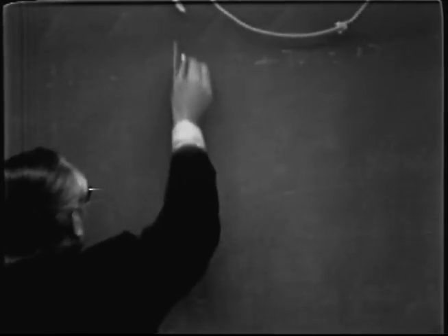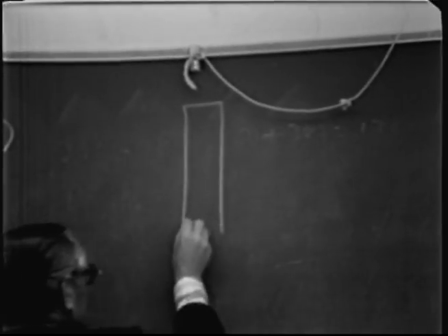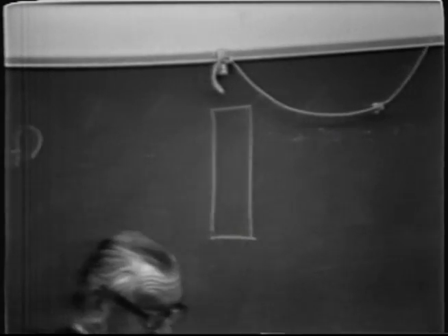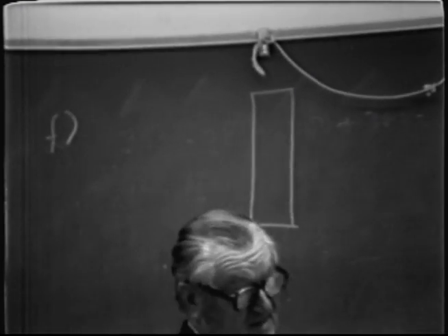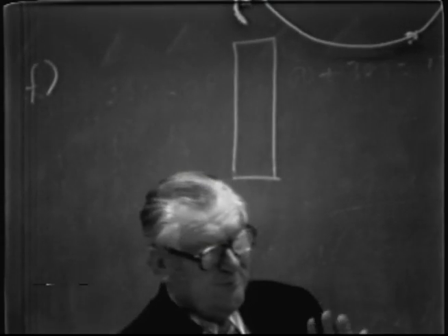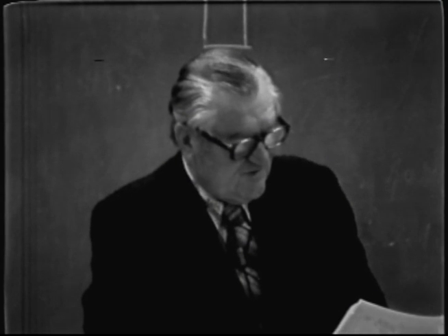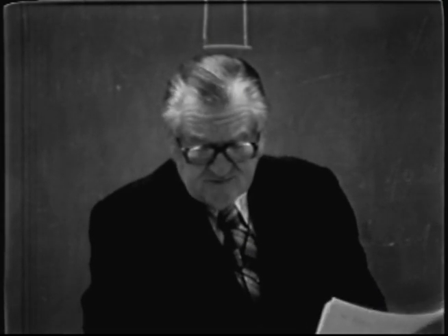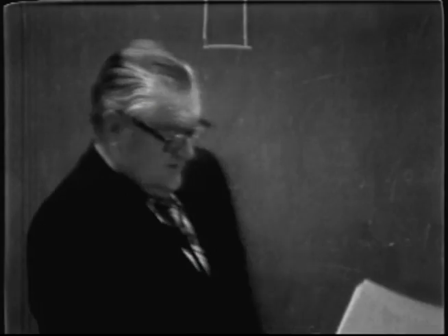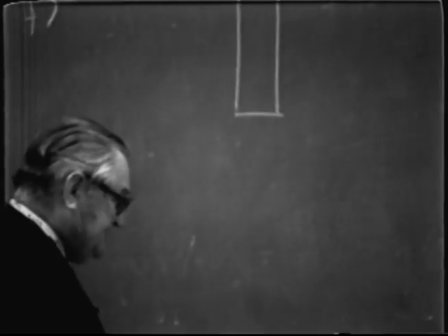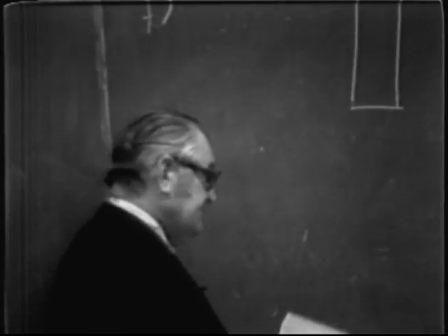First of all, as I'll elaborate on more later, for most of the types of problems we have that involve some aspect of process, such as a distillation process, one of the first things one should do is draw a little simple sketch showing the flow diagram so that you can visualize what it is about.